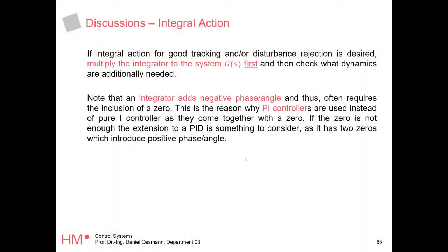Okay, let's go back to the integrators. An integrator basically adds, again, negative phase, right? Poles always make your system slower. So this is actually related to this question. Whenever you can, try to add zeros, because zeros make your system faster, more stable. Whenever you add poles, you add lagginess, right? A pole is always a lag, and lag is usually not a good idea for control systems. You make your system slower, you make it less damped, and so on, right? So you can take it as a rule: always try to add zeros to add an angle and not make it even worse, right?